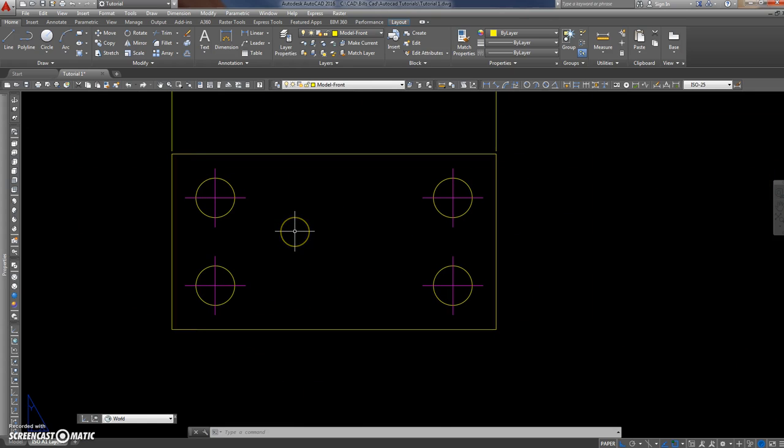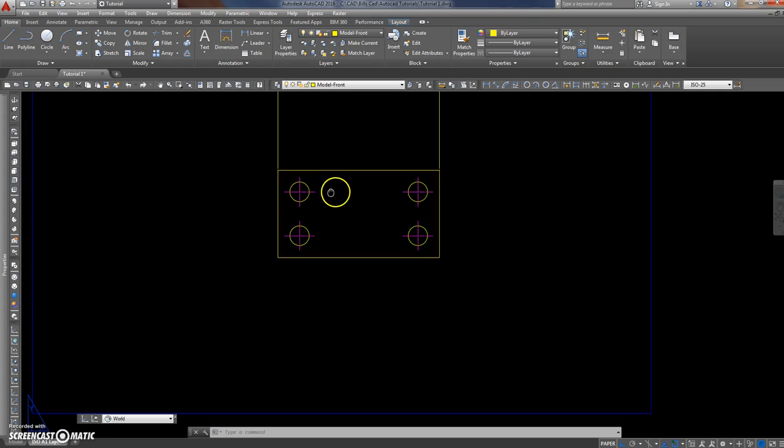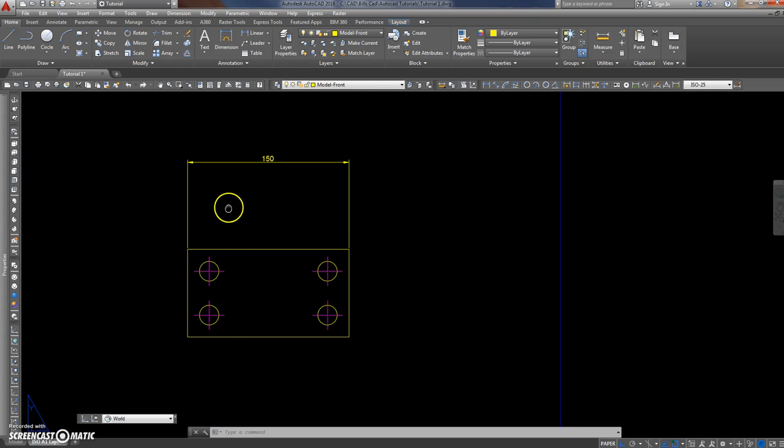This could be the LT scale. LT scale, in other words, that's line type scale. I've just typed that down in the bottom there. Hit enter. See, at the moment it's 1. Let's try 0.2. Let's see if it, now we're getting a little bit of a thing there. Let's try it again, 0.1. And there's some decent sort of line types. You can experiment with all these to get your line types looking good.